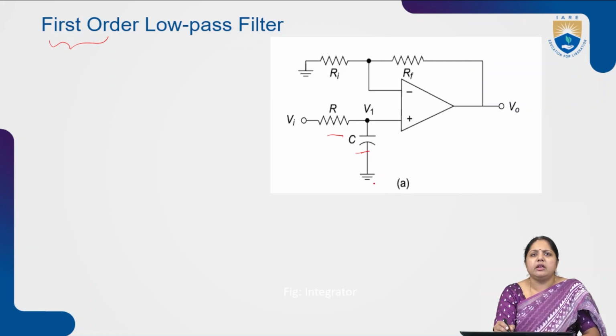Based on the required frequency response, we can increase the order of the filter to get an accurate output voltage value and an accurate frequency versus gain graph. For the best filtering operation, I need to increase the order of the filter, which means I need to increase the number of RC sections.